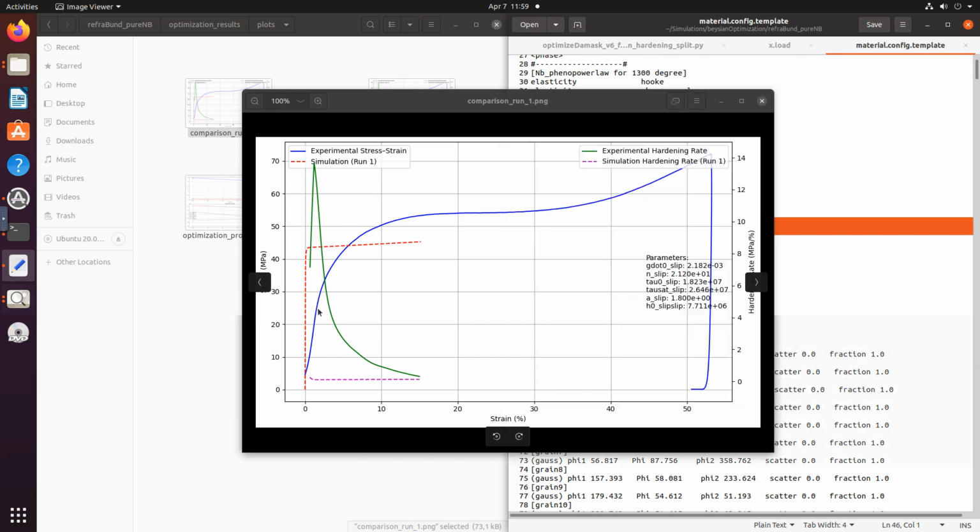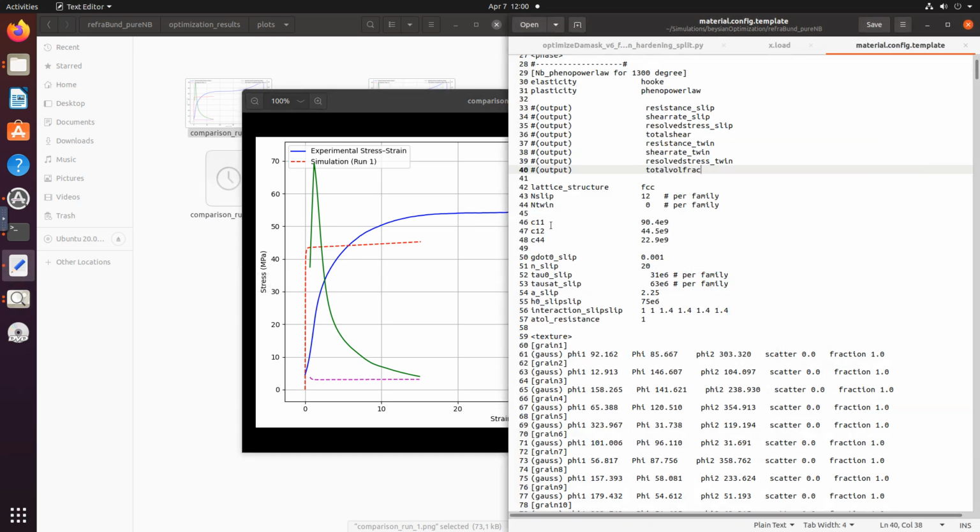So this is my experimental data. I look at the slope of this line. You can find the slope from anywhere you like, right? From this slope, you can use formulas to convert Young's modulus, or modulus of elasticity, into C11, C12, C44. There are formulas given.